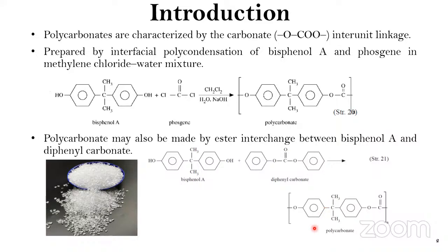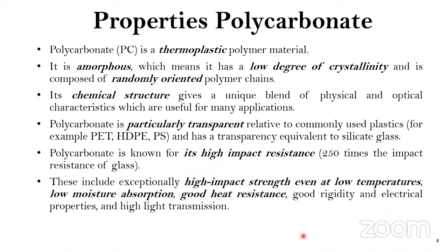And good rigidity. The rigidity is due to the presence of two benzene rings across this alkyl group. Due to the presence of this ester group and this ether group, they help with the flexibility, but due to the presence of these two benzene groups, they form good rigidity, as well as electrical properties.